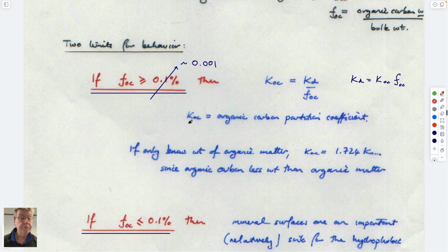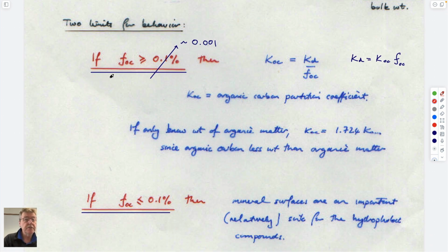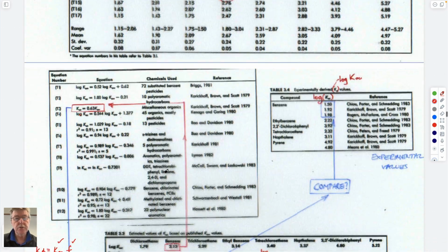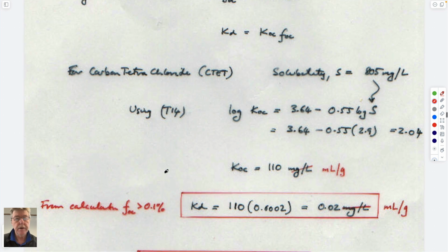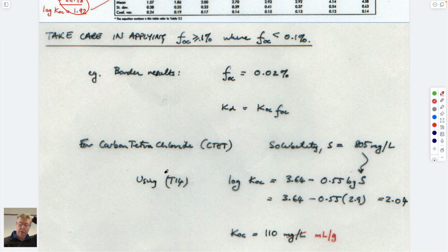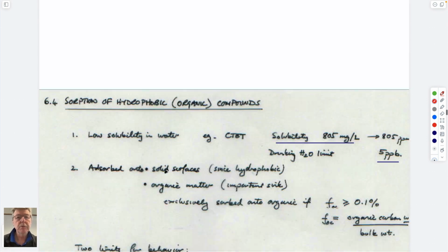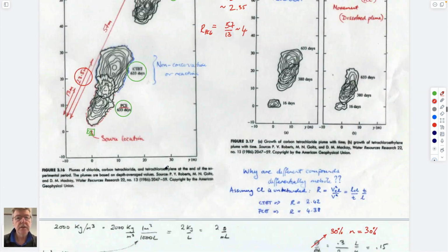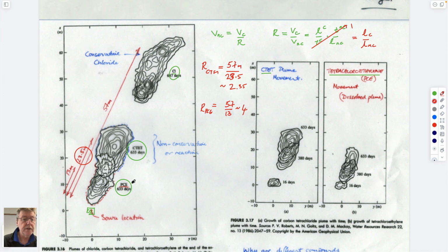So, what was I saying? So yeah, the caveat is you can only use them if there's enough organic carbon in the aquifer. So what we could do is try using that with the Borden data. The two clouds going downstream that were sampled, both with chloride ion and with carbon tetrachloride. So you remember when we talked last time about retardation at Borden? We said that if you have a cocktail that you release that includes chloride, sodium chloride, dissolved ion would be chloride, carbon tetrachloride and PCE.